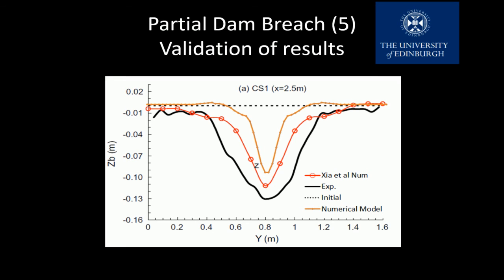And also, because it's a shallow water model, when you have a scour hole like this that forms so quickly, and you have the water coming down almost vertically, the vertical velocity isn't necessarily negligible, even though I've assumed that it is because it's a shallow water model. So these discrepancies could be to do with the sediment, which I'm extending to include more sizes of sediment, but it also could be one of the limitations of the shallow water model.